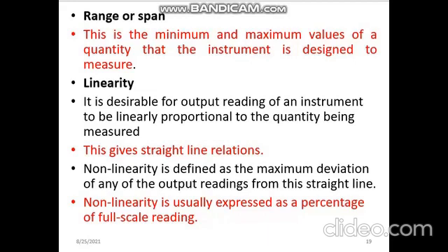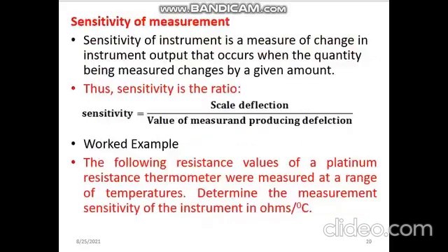For a system to be proportional, it has to be such that whenever the input increases by some percentage, the output also increases by a similar or very close percentage. That is what we call proportionality. While for additivity, suppose you have an instrument whose input is x1 and it gives output y1. When the input is changed to x2, it gives the output y2. So when your input is now x1 plus x2 and your output is y1 plus y2, we can say it has what we call additivity. And these 2 parameters are the most important in detecting whether the system is linear or non-linear.